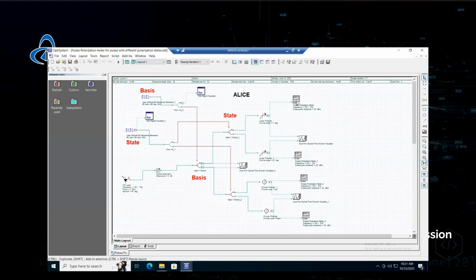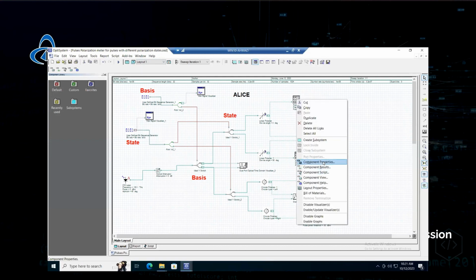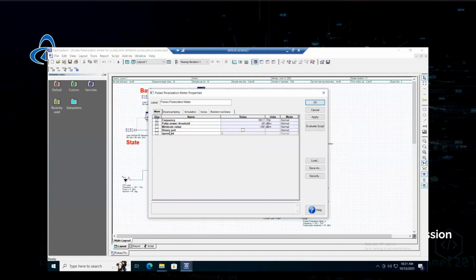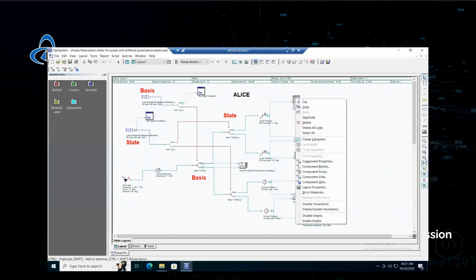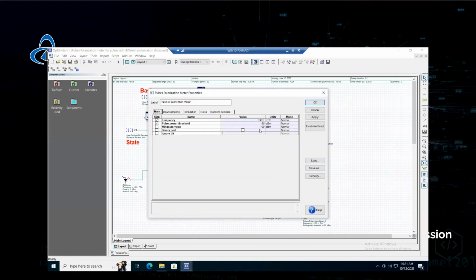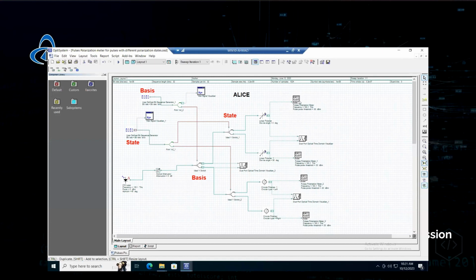As you can see, when the component is set to false for the binary port, you have only a single input port, and for the pulses coming in, you look at the power level. You need to set a level to determine if this bit is 1 or 0 in terms of power. You can set the pulses power threshold, and then you can tell that this bit is 1 or 0 from the power threshold you set.